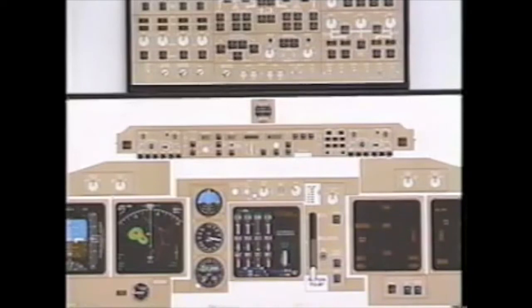If you do not punch that autopilot off, that single autopilot can take you all the way down the ILS, all the way to the runway. It will not flare, and it will bank to track the localizer. So minimum altitude single autopilot ILS is 100 feet AGL. Minimum altitude single autopilot non-precision approach is 50 feet below the MDA. Minimum threshold crossing height for the auto land on the ILS approach is 42 feet.